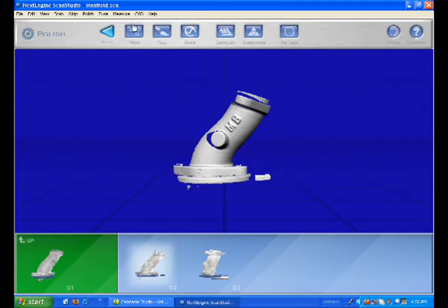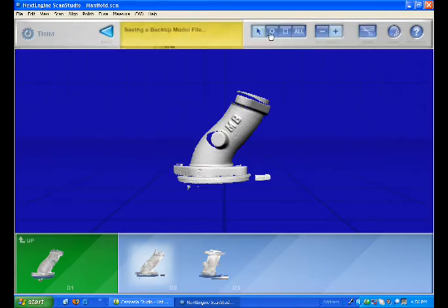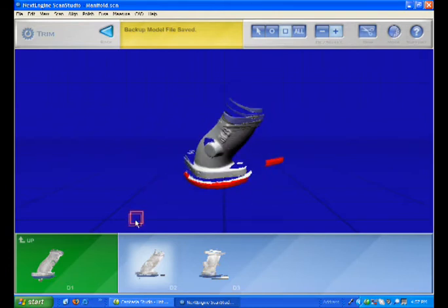So we're going to go to the polish menu, go to trim, and you can see that we have some areas of the turntable that we captured there. So Ronnie's going to go ahead and basically trim those out. You have the option, he picked the square there, you also have the option of the circle, but what we're going to be doing is removing data because we got the plus highlighted and the square. So Ronnie's going to highlight those, and so you can see this is a pretty fast process. He just highlights the areas that he wants to remove, and then it's just like a paint tool, and then he's going to click on trim, and it's going to remove that data.